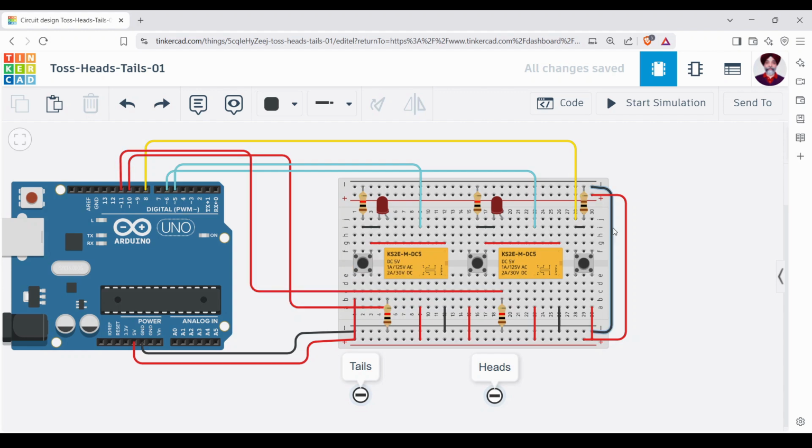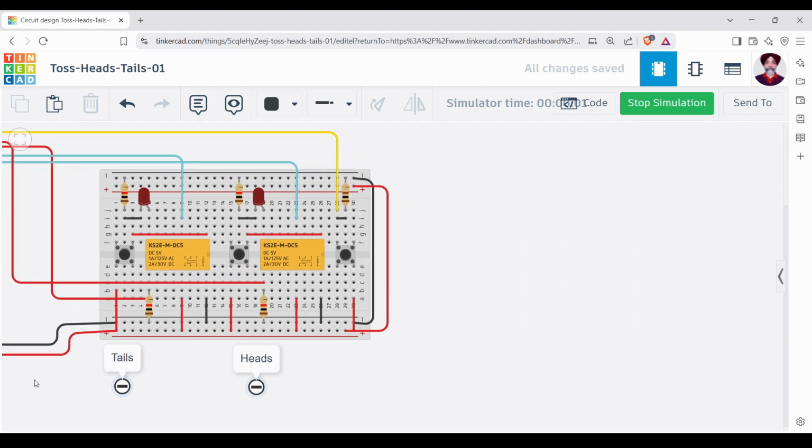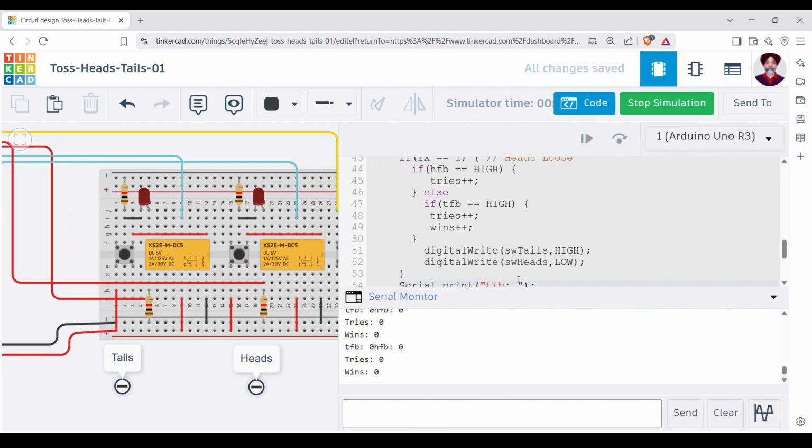That means if this particular pin is not getting anything, it actually gets a low. Similarly, we pull it down. So pin number 10, when it is not getting anything from this terminal line, actually gets a low. So we have now figured out how things should happen. Let me show you the system.